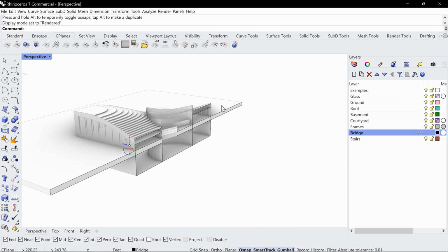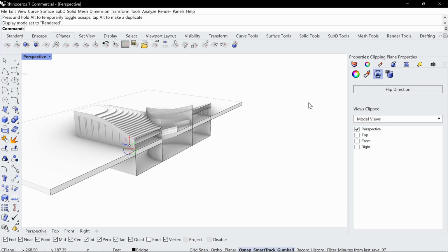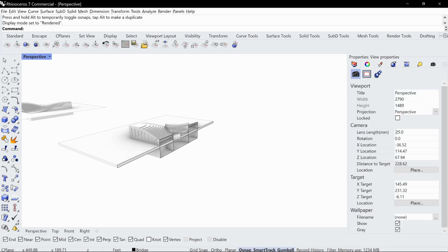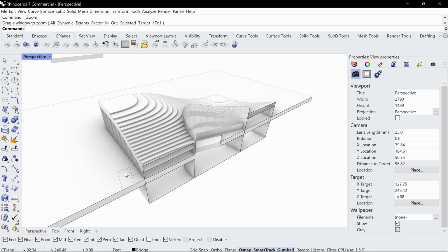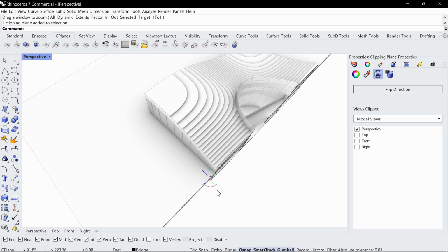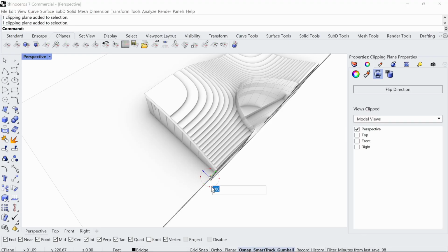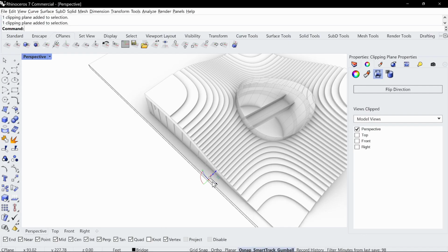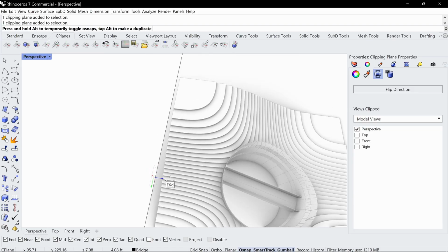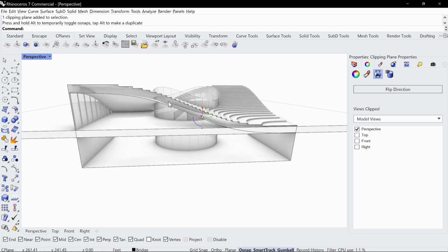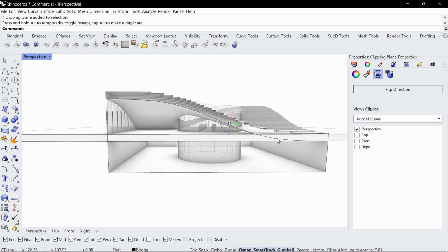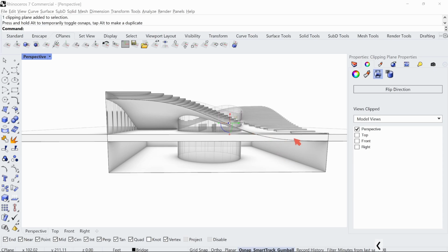And so I like to always update my camera angles. I like to stick it around 25 and 30. So let's stay at the 25 angle mark. And for the clipping plane, let me rotate the clipping plane. Let's rotate it negative 90, like that. And let's pull here, just so I can show you what we will do next. So I mean, first off, this looks really clean, right? As a section. What we're going to do in the next videos is get rid of this so that this becomes open to below like that as a section. But for now, we'll keep it.